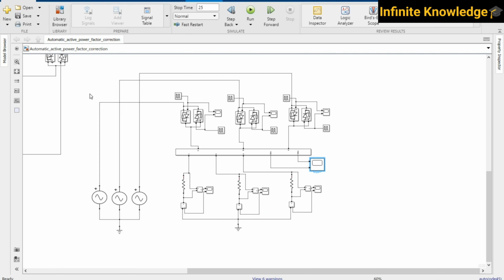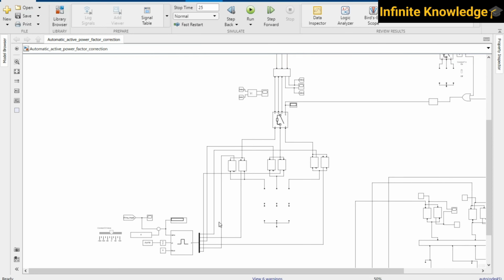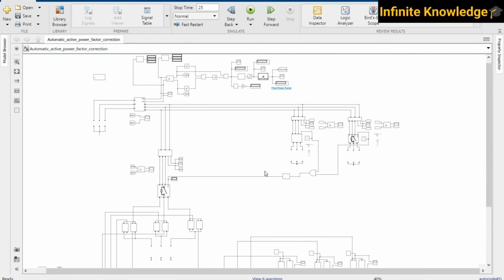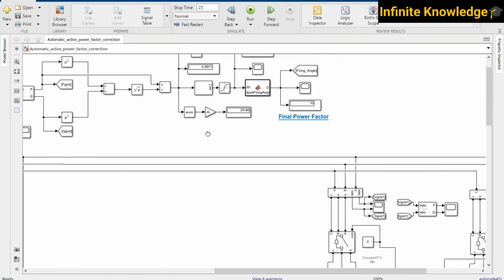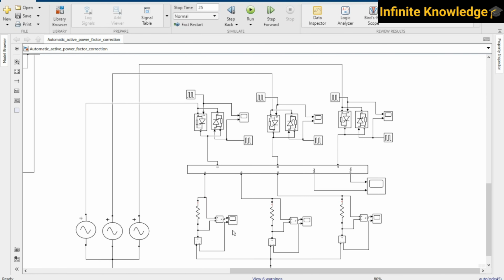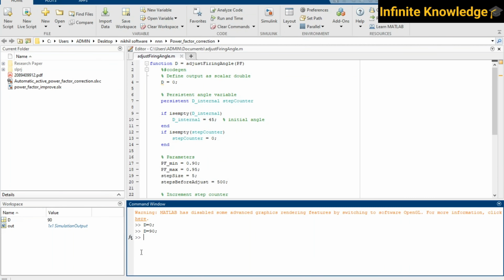So this is the logic that I have implemented over here to switch in the capacitor bank. This is how it is working, and the firing angle is set by our logical controller, a MATLAB function that is PID based. This is why I was explaining this triac system initially, and there is a resistive load, so there is no delay between voltage and current.